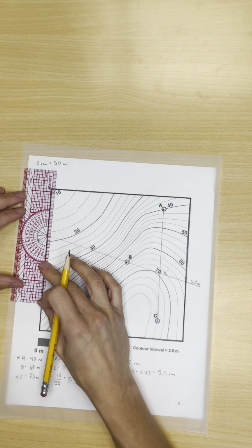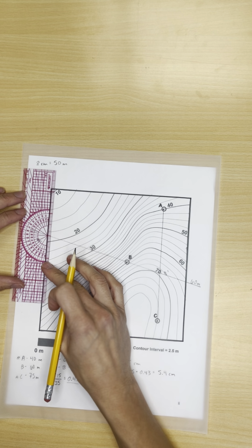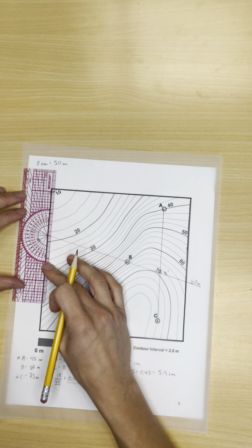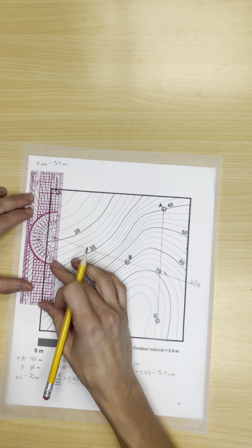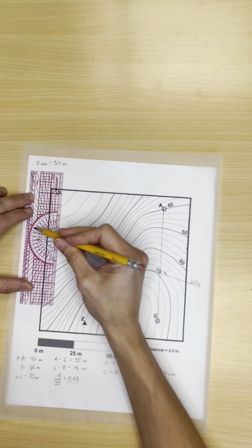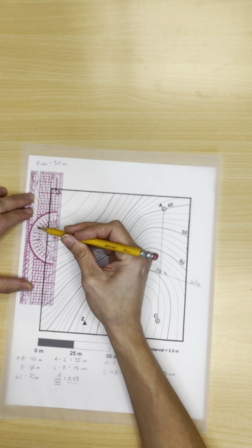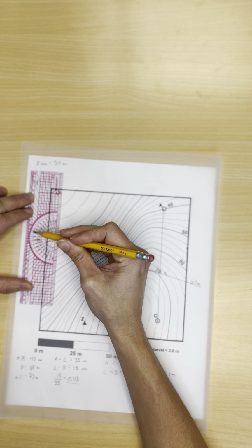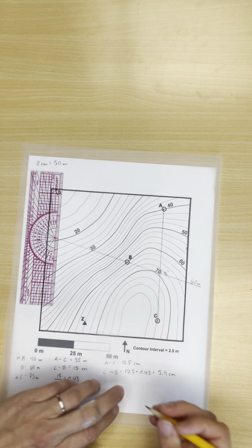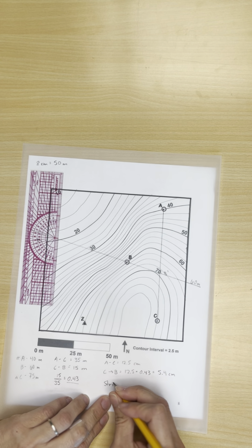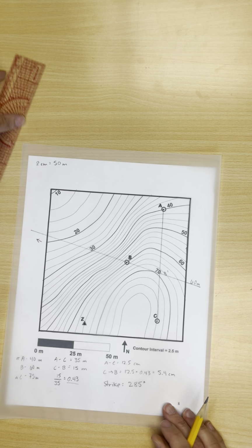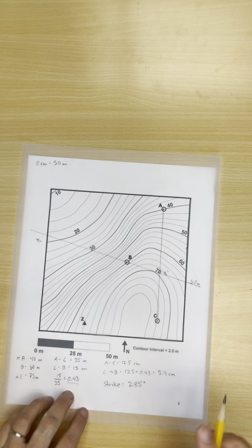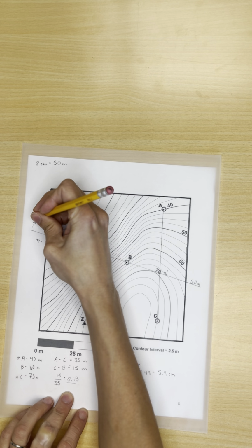I have a little bit of glare coming in here, so pardon me if I stick my head right in the way. Okay, let me move that in a little bit. So that's going to be 75, 76 degrees coming in that way. So that's going to be 270, 280, about 285 degrees. So our strike is 285 degrees. So we got our strike, and we got our dip direction, which is that way.